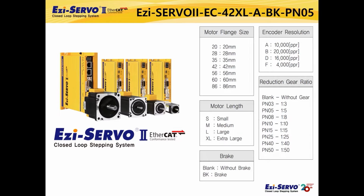In the example model name, EC means the product using the EtherCAT network, 42 means 42 mm motor flange size, and XL means motor length. A means a product with 10,000 ppr encoder applied. BK means that a brake is attached on the motor, and PN05 means that a planetary gearbox is attached on the motor. You can select the motor from a NEMA 8, 20 mm size motor, to a NEMA 34, 86